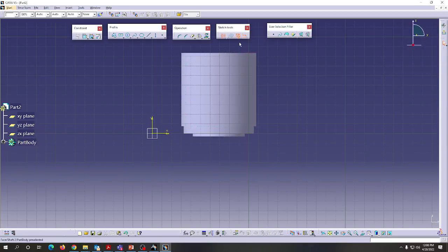So after I transformed my sketch to sketcher mode, I'm just clicking this profile toolbar. I want to go here, projected silhouette edges. I want to get this edge toolbar. I'm just clicking here. In that I want to make the construction line. With this construction line, I'm going to make the profile for the handle. So I'm just clicking it. This one I don't want, so I'm just deleting it.